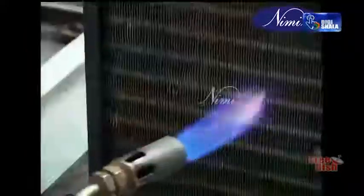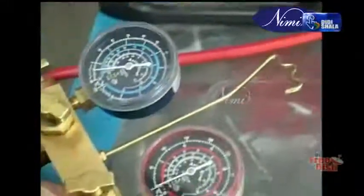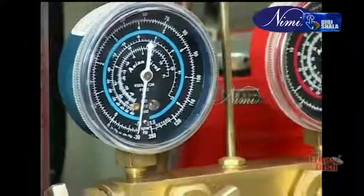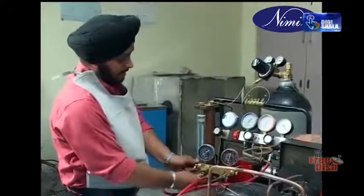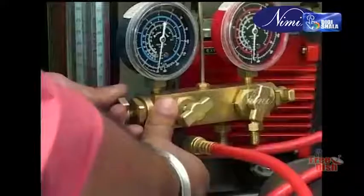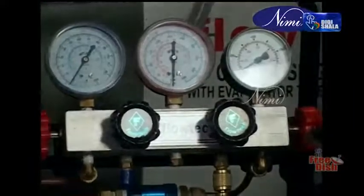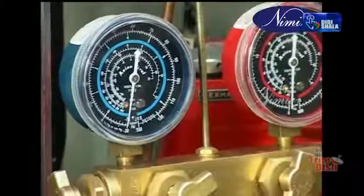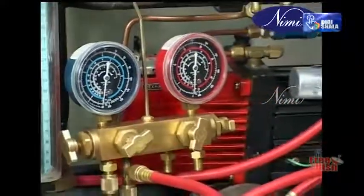During evacuation, dehydrate the system. Both the gauges of the manifold show vacuum up to 30 inches of mercury, 100 microns, within some time. Now close the manifold valve where the vacuum pump line is attached. Let the system stand in vacuum position for at least 2 hours and check if there is any shortfall in vacuum. It should remain standstill at the same reading.